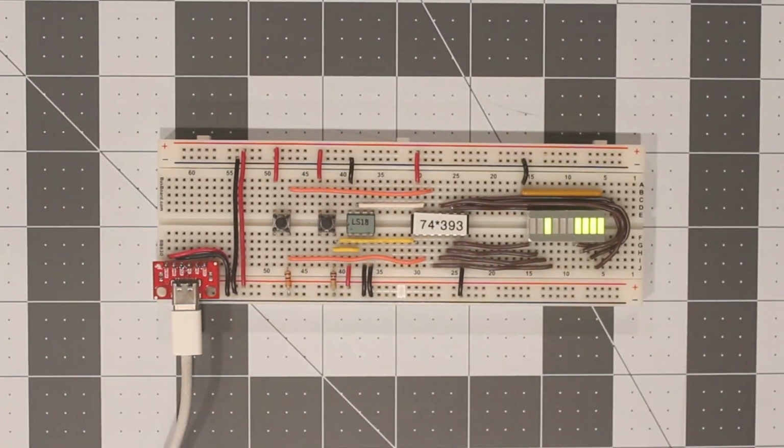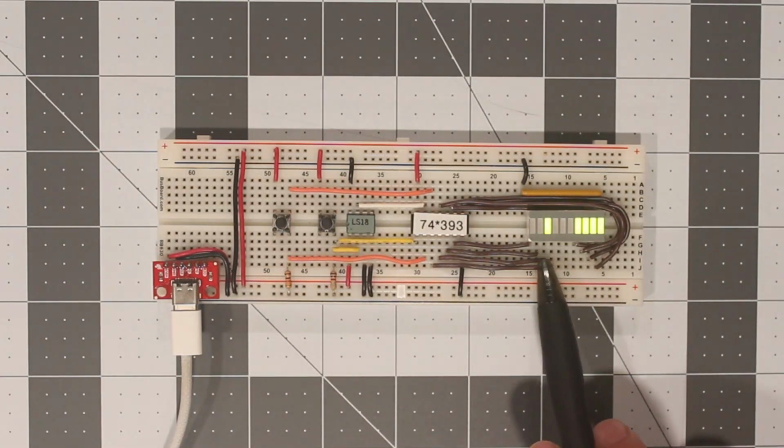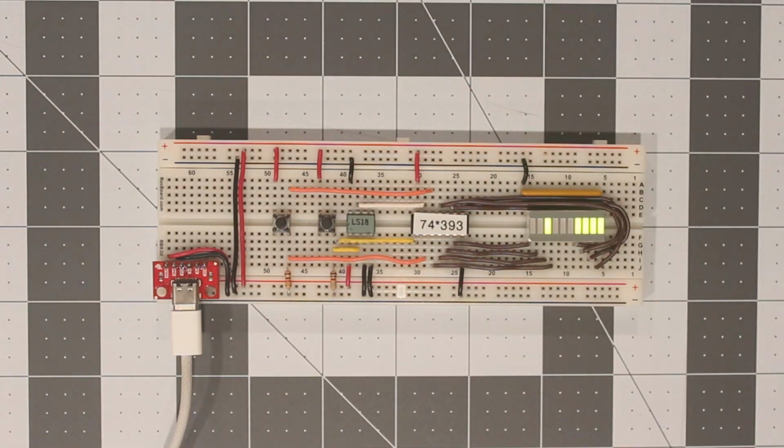After the test, we can see that the right 4 bits of the LED are set high, meaning that the counter did increment exactly 15 times as desired. The left side of the LED shows the results of the original circuit, which triggered the counter directly from the noisy switch. This counter shows that it was incremented an undesired 3 additional times.